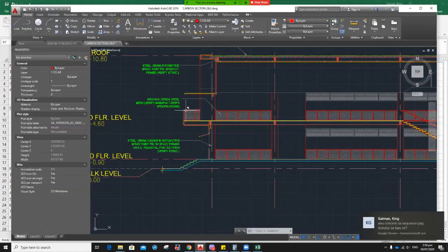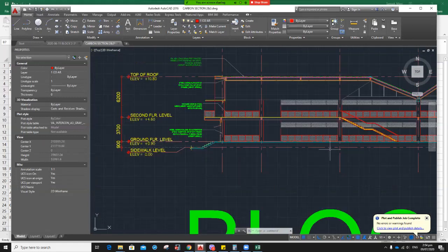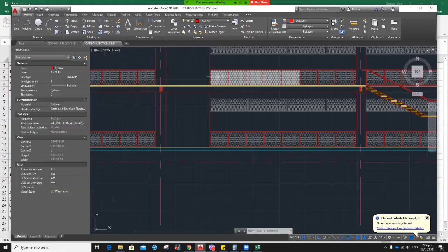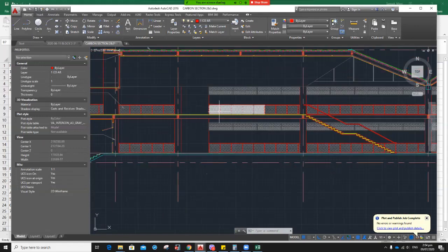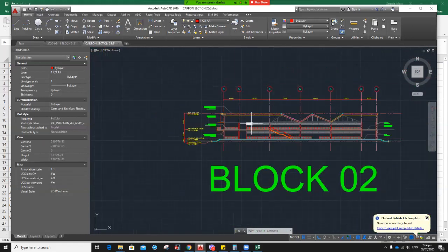Okay. So for the beam load, these walls, these partitions, although quite light, if this will be steel, then it might already be considered in the floor load using the movable load because it's very light. But if you will be using concrete barriers there, then it will be very, very heavy. Okay.